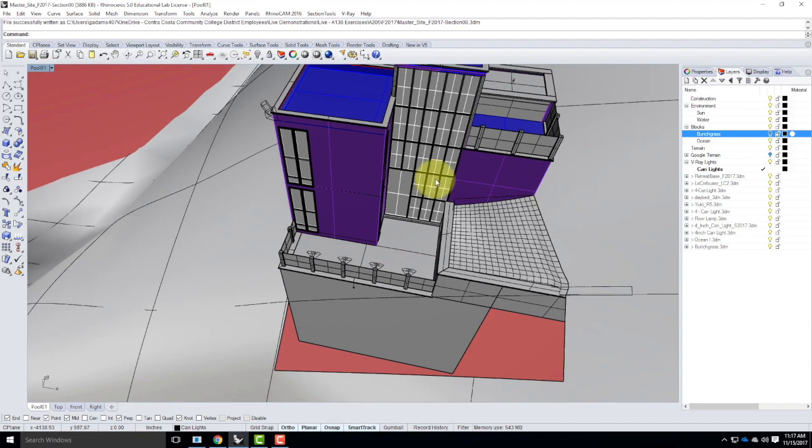Generally speaking, when you cut a section, you want to pay attention and think about what's the best place that I could be cutting a section. If you look at your model and you say, I don't know where to cut the section, or there's not really a good place to cut the section, your building's probably not very interesting. So there should be some really magical moment that you want to cut through. Okay? So in my case, stairs are always a good place to start. If you have stairs, cut through the stairs. When in doubt, cut through the stairs.